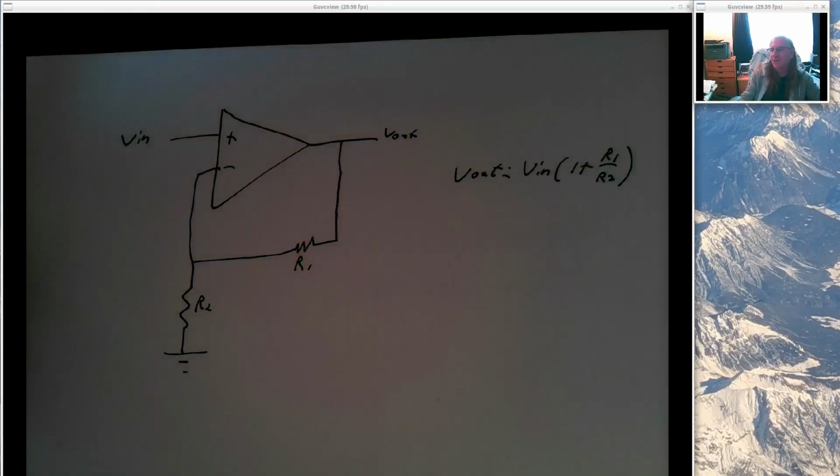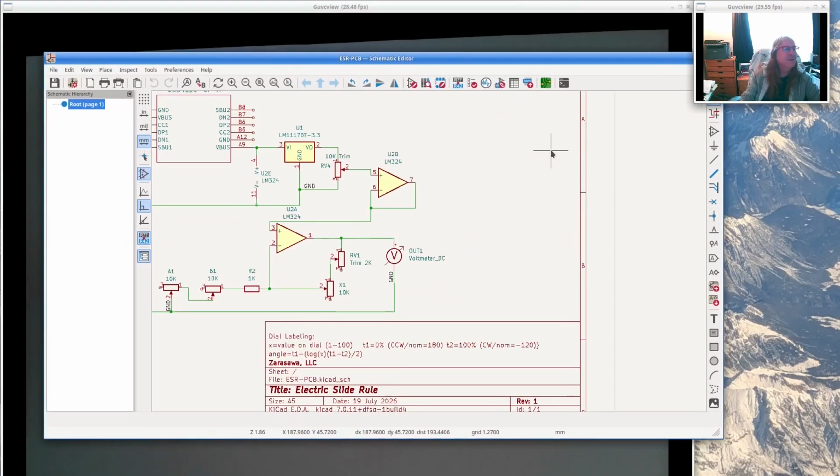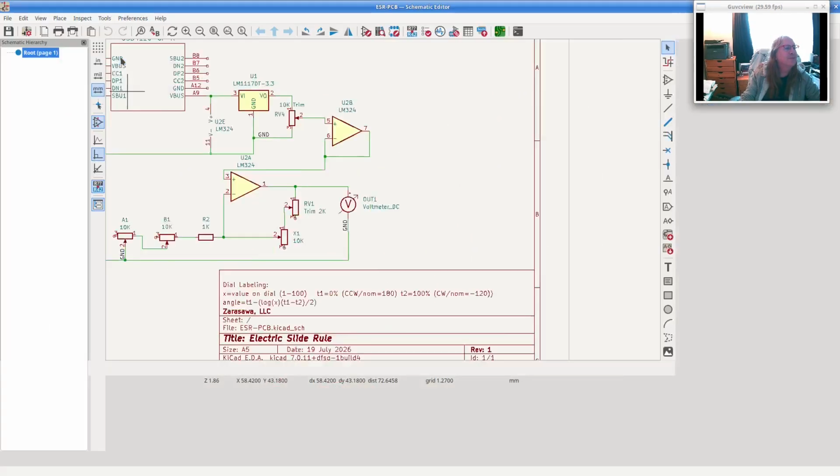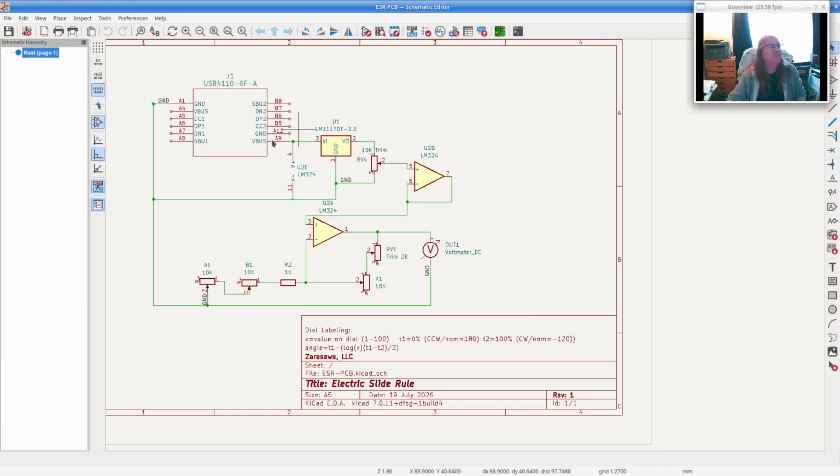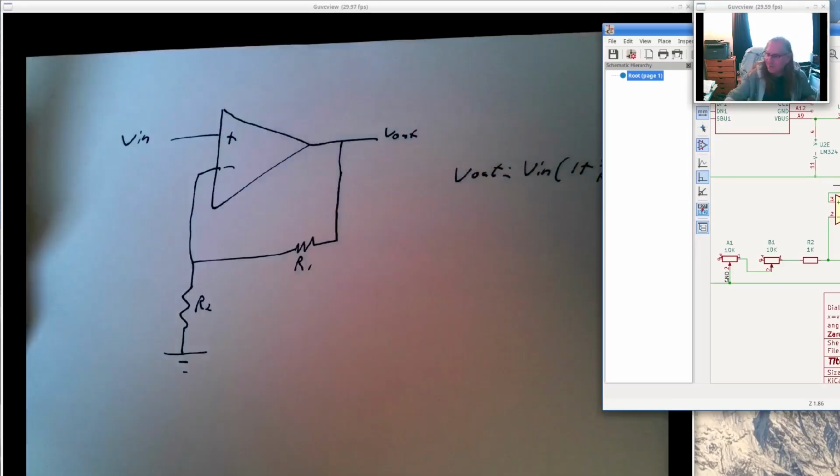So that led to this idea of let's go ahead and make a circuit with an op amp, and it looks like this. So this is just power coming in from a USB port. I'm going to get a 3.3 volt regulator, so I get a very precise 3.3 volts, and we're going to trim that down through a precision trimmer, so a very fine tunable potentiometer, to 1.25 volts, 1.25 volts going into here. This is just a voltage follower that insulates the input from the output.